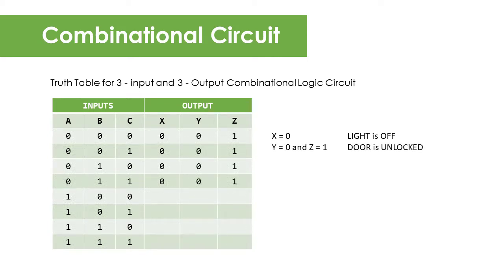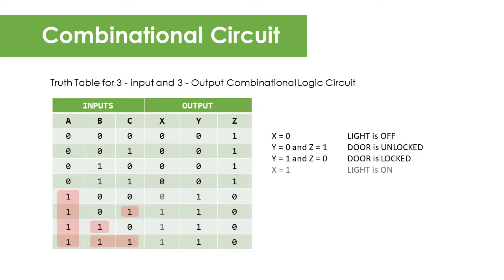Say one of the pins of the solenoid will receive ground and the other pin will receive 5 volts. This puts the solenoid in a push state simulating the unlocked door. However, when the main switch is activated or switched to logic 1, then regardless of the status of the two light sensors, the solenoid must reverse its state into pull state simulating a locked door. In addition to this condition, the light bulb will only turn on as long as the main switch is activated and at least one of the light sensors detects dark surroundings, assuming nighttime.